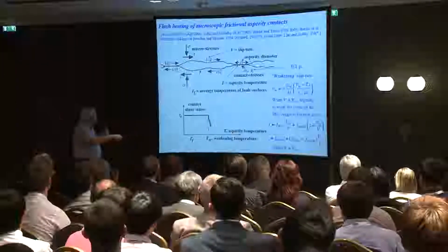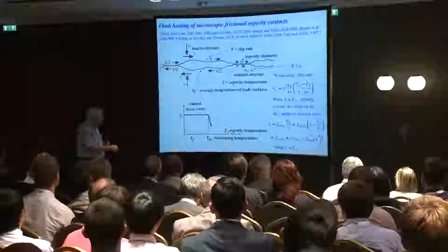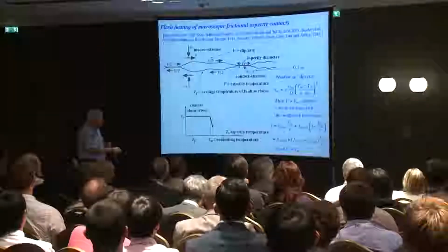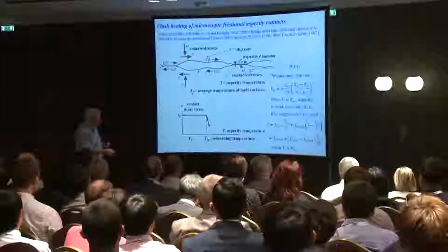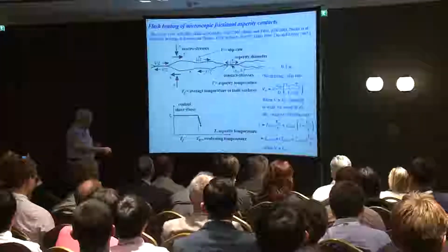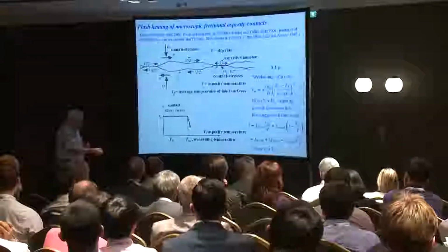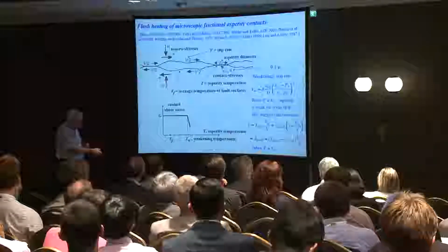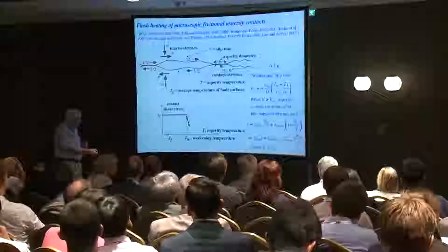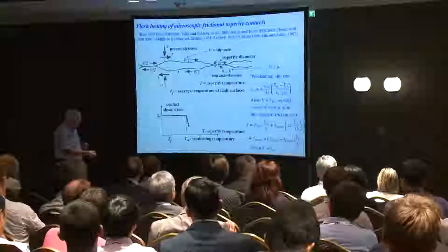It will get slid out of existence, but if it is just going to reach the weakening temperature as it slides out of existence, and then the friction is negligible or some very small value, that would suggest a friction law, which is the friction factor is high, slow friction when the velocity is small, but when the velocity is high, asperities weaken during their lifetimes, and you get this other factor.